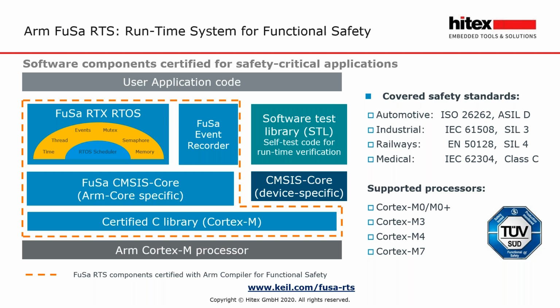Most libraries that are self-written will get a coverage of between 30 to 60%. Whereas you need quite a deep understanding of the processor to write a successful test library. So the ARM-derived ones typically will cover in excess of 90% of the gates. So again, if you need a software test library, these are available as a separate product and are licensed through the different cores.